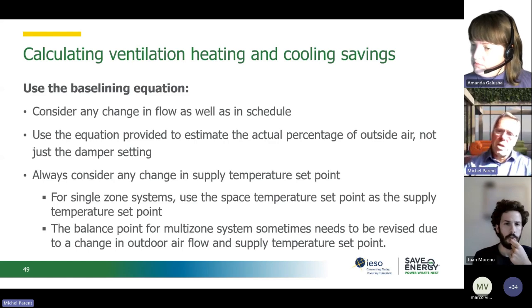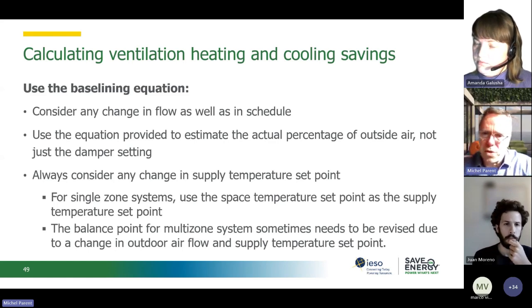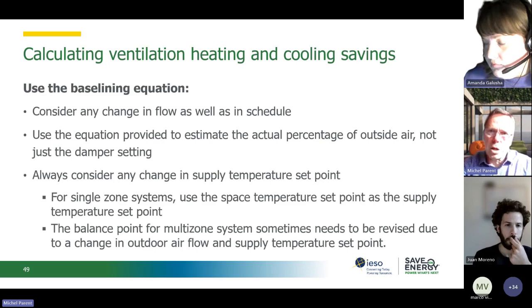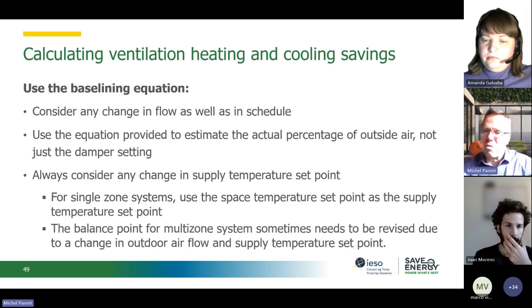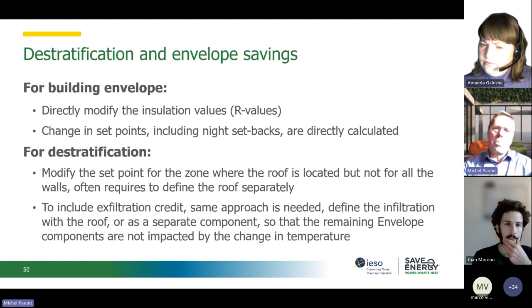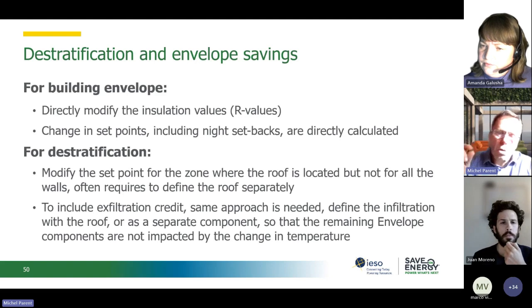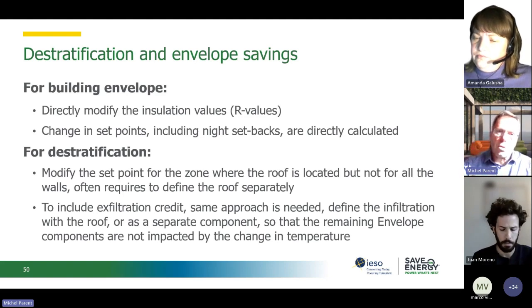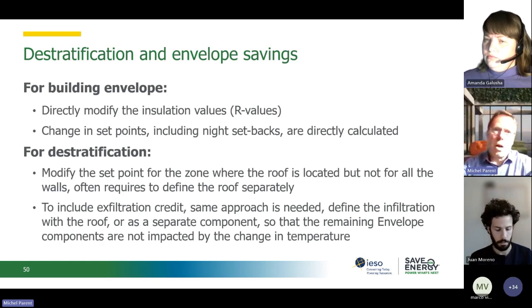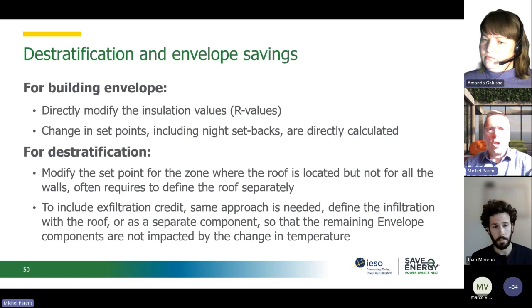When you put a VFD and you say, hey, it's going to reduce the speed by 50%, you have to be very careful about your reduction in speed, because often people will overestimate the reduction. Very often you go on site and you see VFDs and they're running at 80%, 85%. So you've got to be very certain of your reduction in speed that you think you're going to achieve, because that is then exponent to the third, or 2.7 if you want to be more conservative. So it's really going to blow up your estimate to a very large saving. So be very careful.